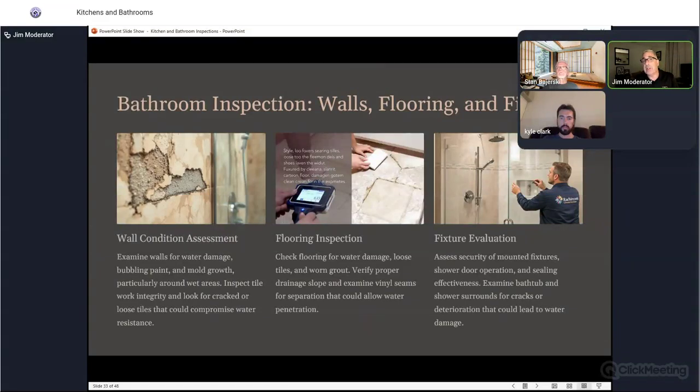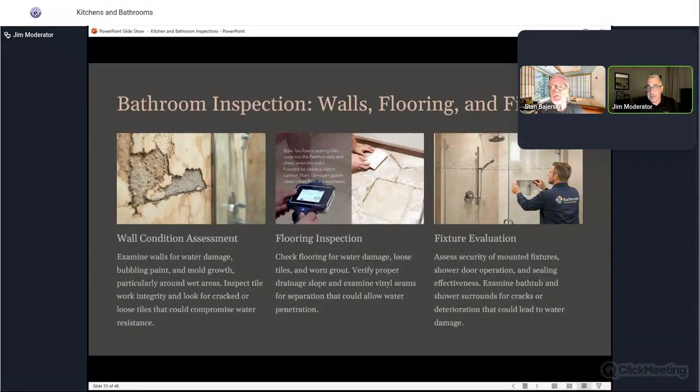It has been corrected by putting a GFCI outlet in there. But it is not going to trip in the proper manner, and there may be an electrician or a handyman that does not understand that. There's nothing wrong. I'm confident that you're going to be safe. But if I have a more experienced client who looks at me and goes, yeah, I get it, I'm just going to put in there that it's GFI protected. So that's how I'll handle it.